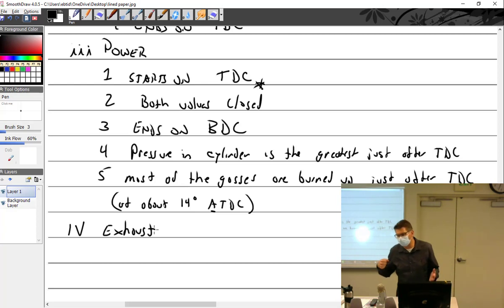It's hitting the piston with a huge hammer, rather than giving it a nice good push. So that's very bad. The gases start expanding while the piston is already working its way down, pushing and pushing. That's why the greatest pressure is just after top dead center. The piston is just starting to come back down, and the gases give their hardest push right about that point. Then it lessens off as the piston goes down.